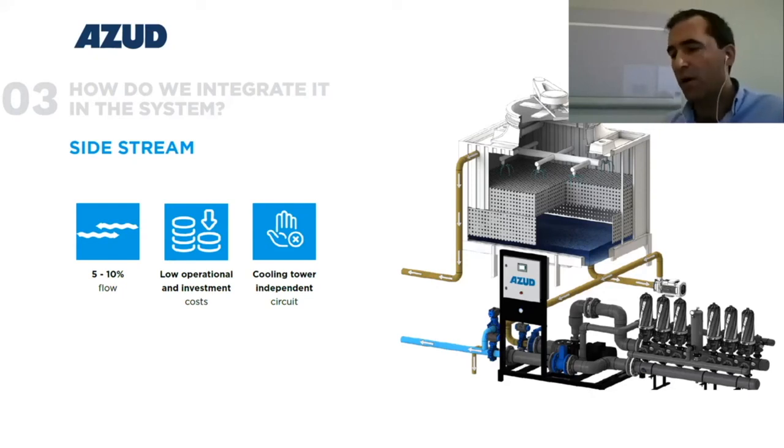The control of biological growth can also mitigate potential health problems, such as those caused by Legionella. The use of a side stream filtration can minimize habitat surfaces and nutrients by maintaining lower particle levels in the water stream.